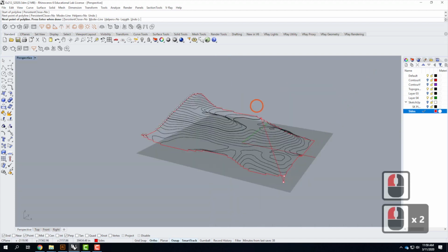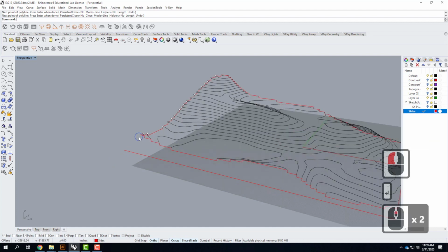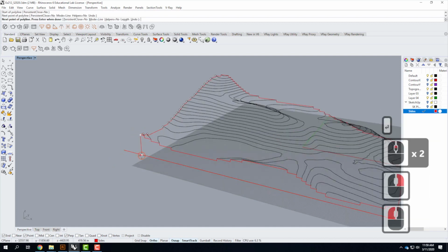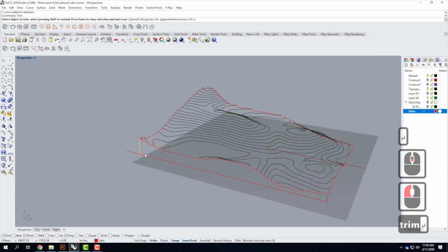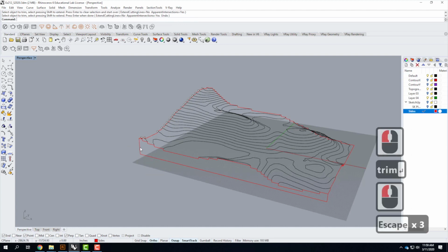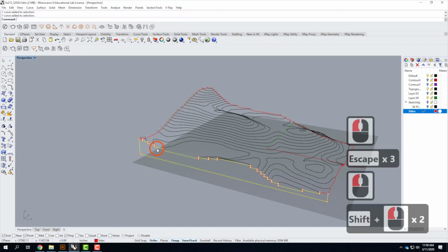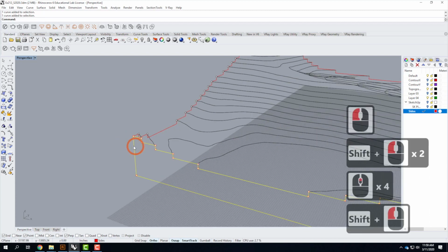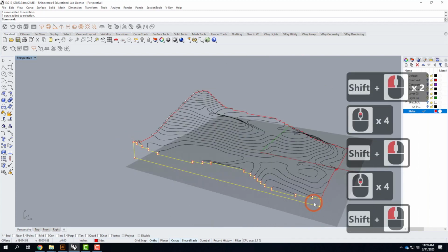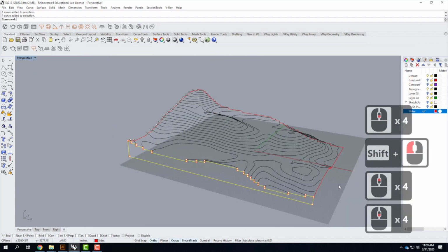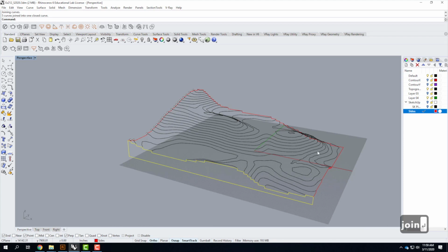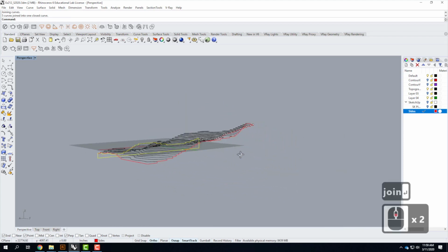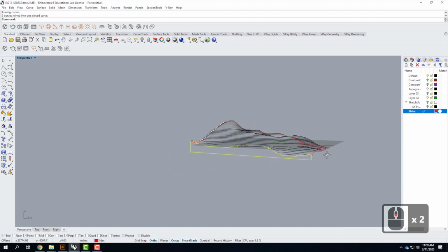And then I'll move back into the perspective view. I'll leave this long. I'll start at this corner and go down and snap to perpendicular. I can then use this as a trim. I can trim that off. And you can now see that I have my first side. And I'm going to go through and select it all to right there. There's my first side. I can go ahead and join that together. It's Edit, Join, or I can type in join, or I can press Control J. And that creates my first side of this little model.